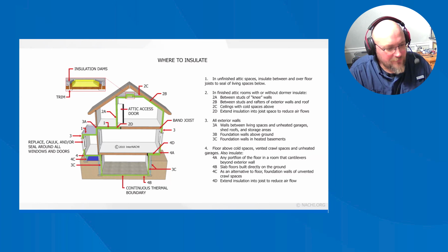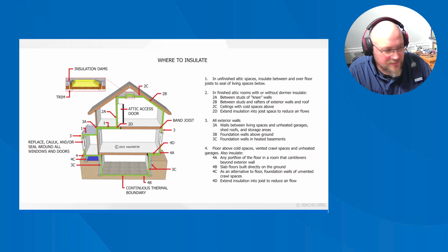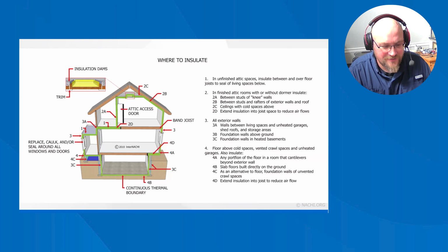So again, making sure that the electrical is solid, everything is prepped and ready. And if you do see new insulation and they blew in new insulation, you can still see open splice boxes. I would highly recommend you call those things out and make sure that your client is protected from a potential fire in their attic.